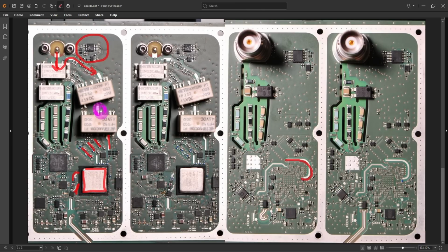Now on the other side, we do have the 1 mega ohm input that itself needs its own attenuation, but it also has an AC and a DC coupling mode, and you can see series capacitors and so on in the front end. And there's another dedicated IC over here which will process that, convert that to differential, and it arrives here as well. So there's a chip in this one. That is most likely a switch, and that will switch and select between which of these paths ultimately gets over here, and that's the signal that's going to reach our ADC.